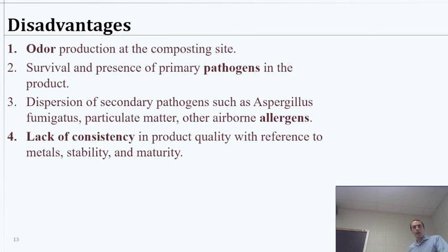Survival and presence of primary pathogens in the product is possible, so that's an obvious disadvantage. Like I said, we would not want to apply biosolids of this nature to anything that's direct human consumption. Dispersion of secondary pathogens, different fungi, particulate matter, allergens, some issues. You might have some lack of consistency in your product if you have different things happening in your wastewater.